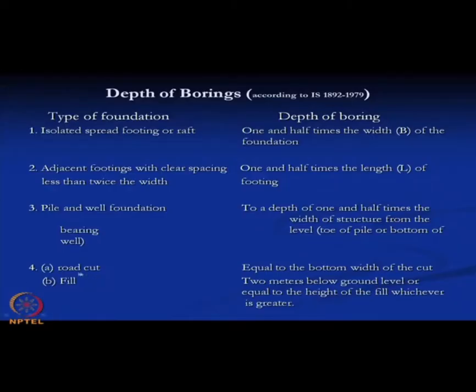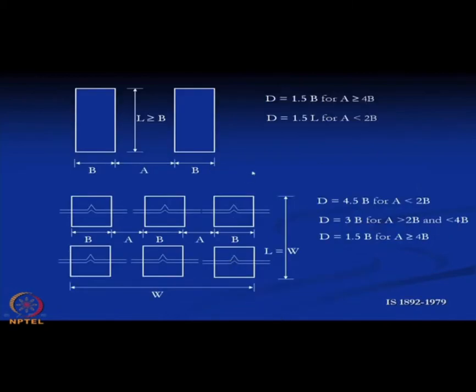Then the next one is the road cut, that is equal to the bottom width of the cut, and then fill: if it is a fill, then 2 meters below the ground level or equal to the height of the fill, whichever is greater.